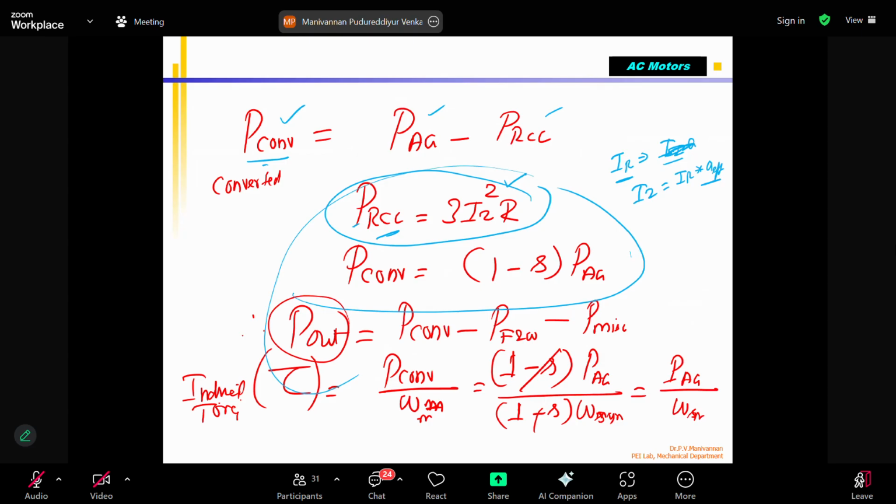I told you the induction motor works like a transformer. So A effective is the effective turns ratio of the induction motor, just like a transformer ratio. If the manufacturer, or the problem, gives A effective, then you need to find out IR. You can find IR already.